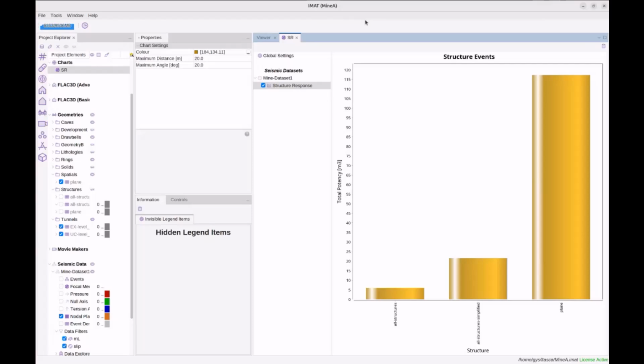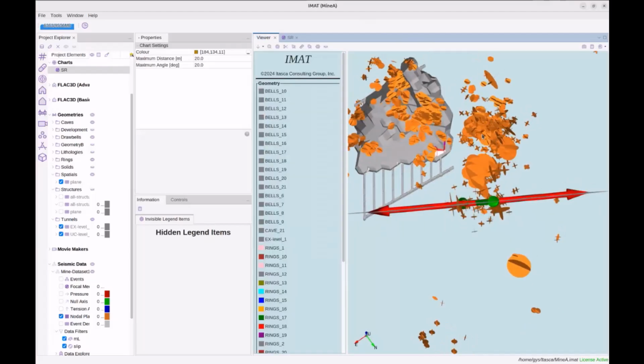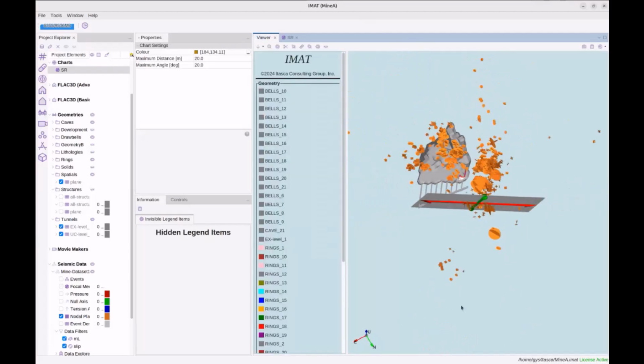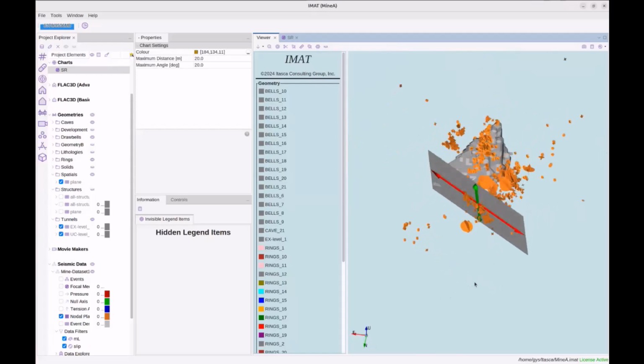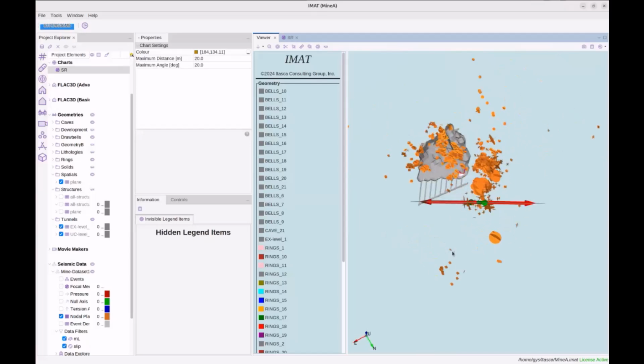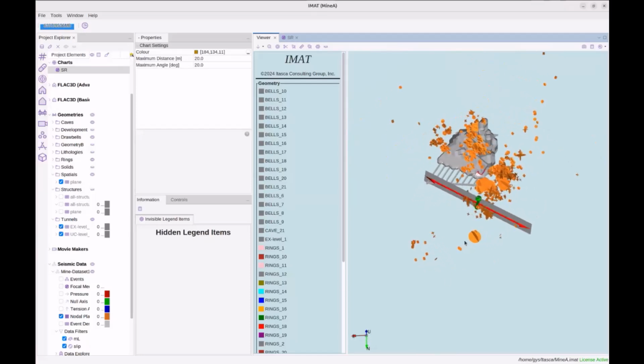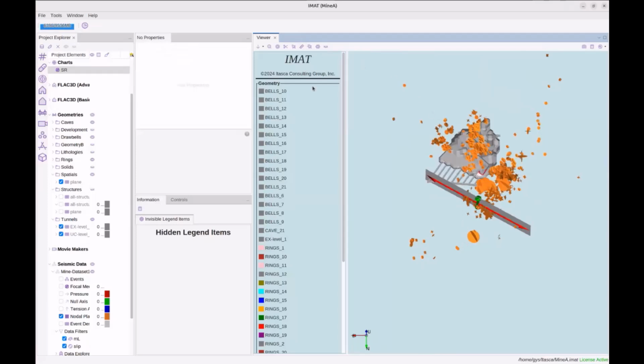But often, many of those structures aren't seismically active. And if we've got good seismic data, as I've illustrated here, adding 100 structures in here, for example, where there's no seismicity, our model might actually show that there's some slip on that structure, but there's no seismicity that we've actually recorded. Then it could be one of the typical examples where that slip is aseismic and not seismic. So I need to question whether or not I really want to add that structure in my model or not.